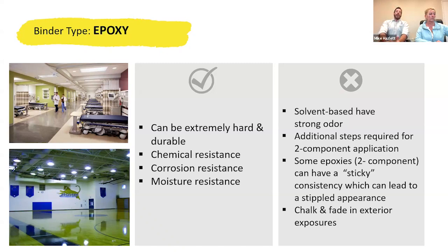And also after that, you have your pot life. And that pot life is how long you have to apply it to the floor or to the substrate before it will literally just start hardening on you. So I get all kinds of phone calls. Hey, Mike, we painted this floor last night. We came in this morning. It's still sopping wet, hasn't dried.